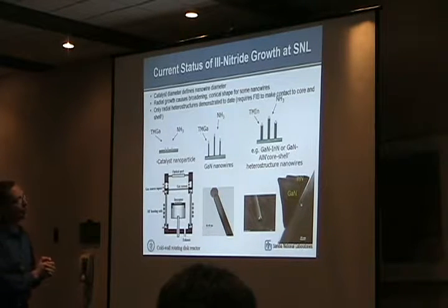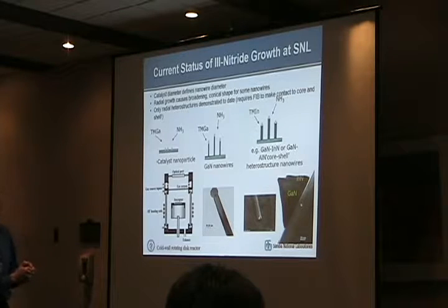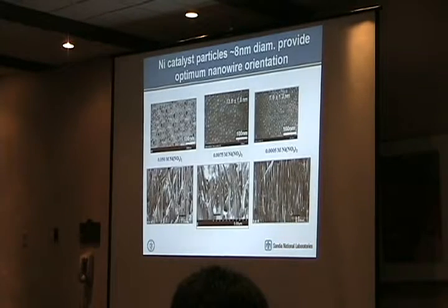Once the nanowire is grown, one can then introduce, for example, trimethyl indium or trimethyl aluminum and ammonia, and grow a core shell nanowire, and you see a cross-section right there. What substrates do you use? I'll talk about substrates in a few slides. But generally we use silicon, we use sapphire and different orientations of sapphire. We use silicon dioxide. Those are the prototypical substrates.